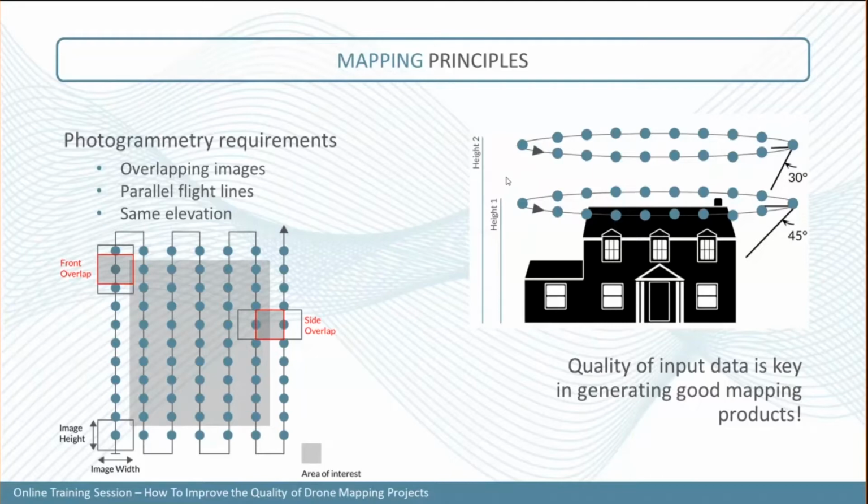Sometimes, if you're flying an area where you have a lot of slopes or features with really high elevation changes, you may want to use a flight planner that gives you the opportunity to use a follow terrain option, so it's going to follow the terrain. Try as much as possible to keep a constant GSD throughout the project.